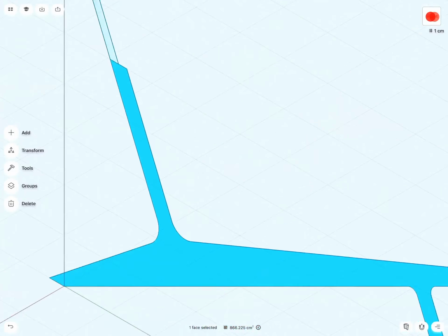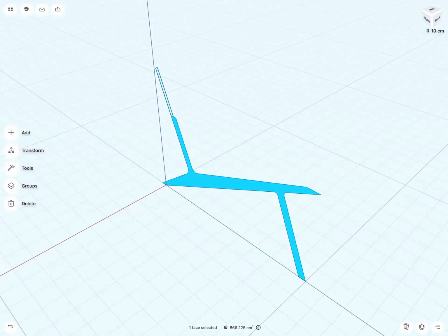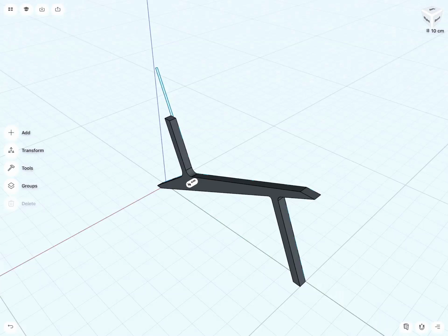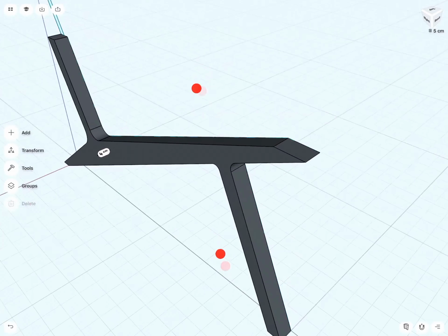I'll double tap on the cube to go into the original orientation so that the grid is on the ground, and then drag this surface forward to generate a three-dimensional solid. I'd like it to have a 4 centimeter thickness. Then I'll zoom in here in this front area.